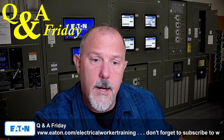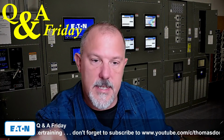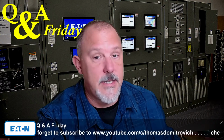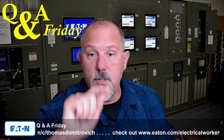So I also think this misinterpretation might be avoided if people remember that the fault current is usually nearly the same for an instant, regardless of the circuit breaker size. That is exactly right, and that's the point. You nailed it right on the head, and that's a good way to look at it, JW. It's the impedance of the source that matters.